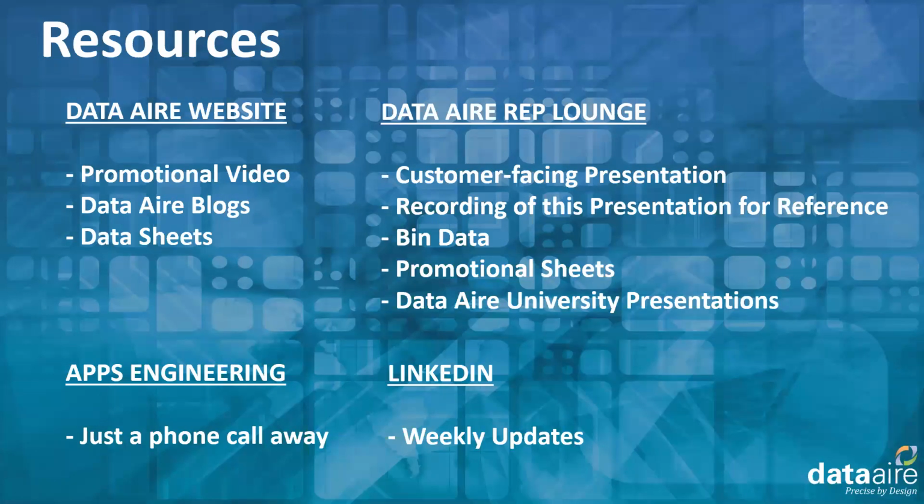Okay, yeah, I'll take that one. In this case, they used a closed-circuit evaporative cooler. So the coils were only exposed to closed-circuit water that was chemically treated, like they're always chemically treated. In other areas of the country, we didn't have to worry about glycol in the system in Los Angeles. But in other areas of the country, you will need glycol.